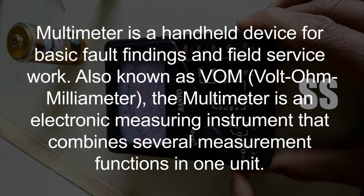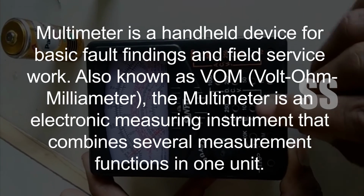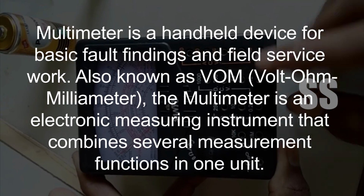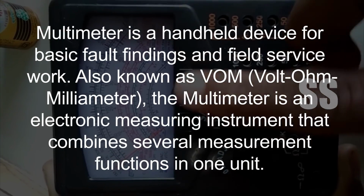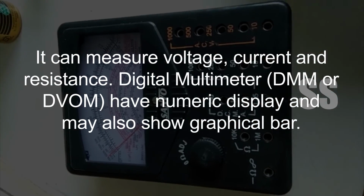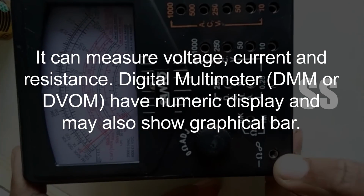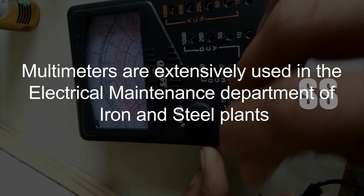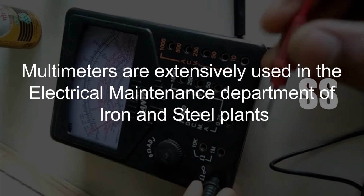Multimeter is a handheld device for basic fault findings and field service work, also known as VOM, volt-ohm milliammeter. The multimeter is an electronic measuring instrument that combines several measurement functions in one unit. It can measure voltage, current, and resistance. Digital multimeter DMM or DVOM have numeric display and may also show graphical bar. Multimeters are extensively used in the electrical maintenance department of iron and steel plants.